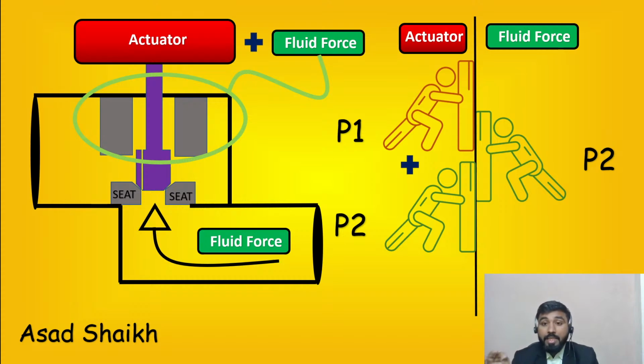The reason is, if your fluid has even smaller solid particles, they will still get stuck in the balancing hole, and your actuator will not be able to function well because it is not designed for that high pressure. Now why am I telling you this?